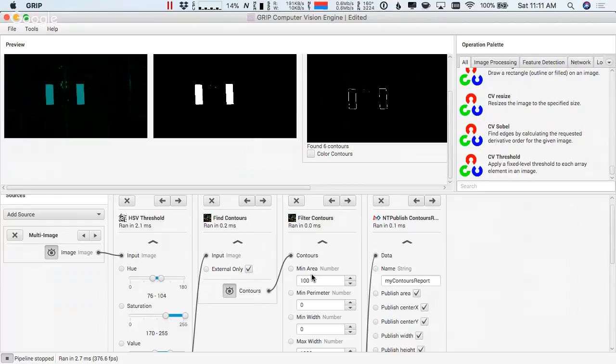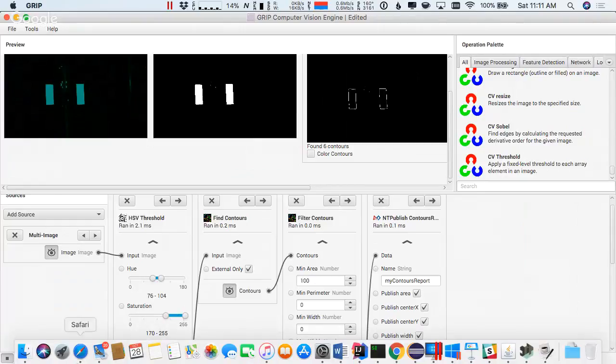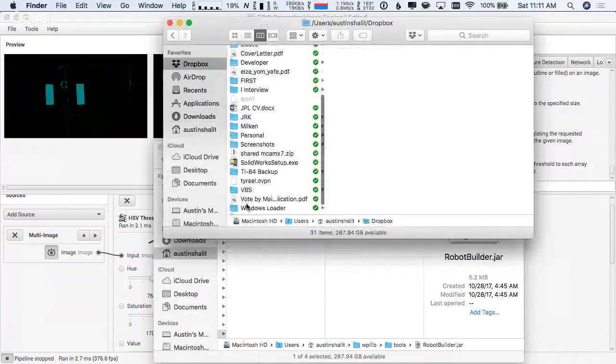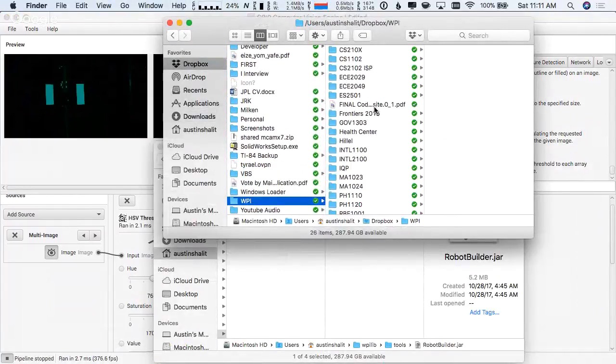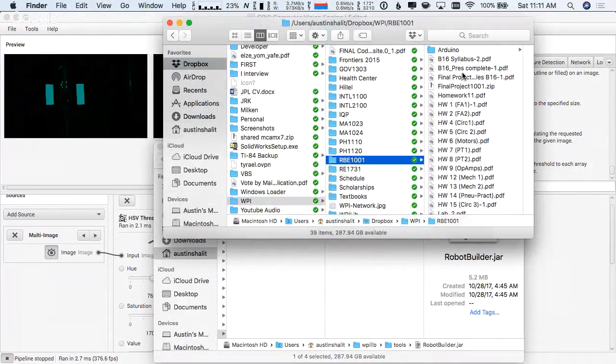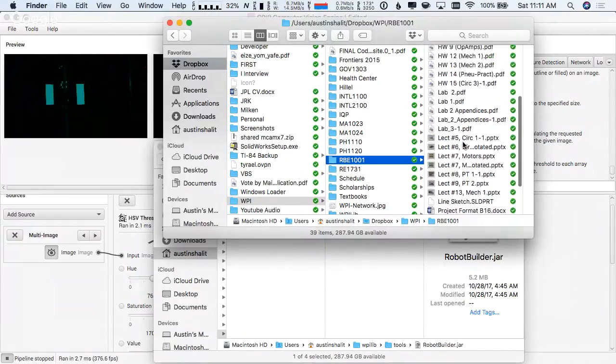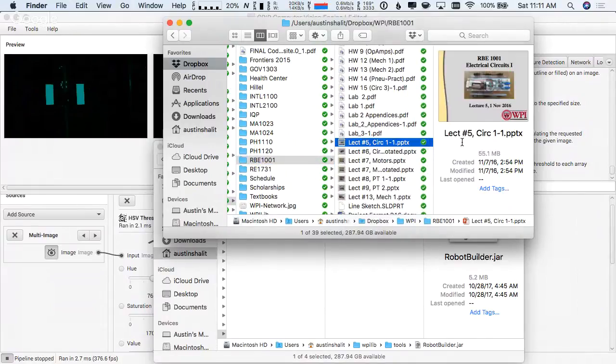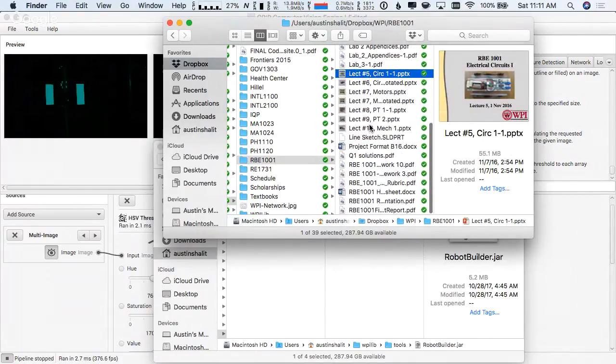Sometimes teams have chassis that are kind of complex, where the front and the back are tied together with a pin in the middle, so they can ride over uneven things like carpet and stuff like that, and it still works. You have to be really careful about that if you're using these wheels. Here, I actually have a little demo. All four wheels have to be in contact with the ground at the same time, or you won't be able to get the thing to drive in a straight line autonomously. Yeah, most FRC frames are flexible, and often they're flexible enough, so that might work.